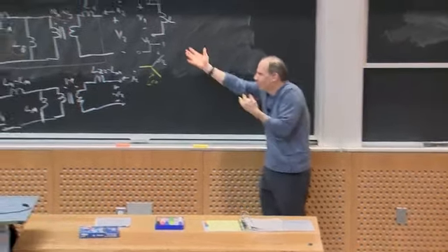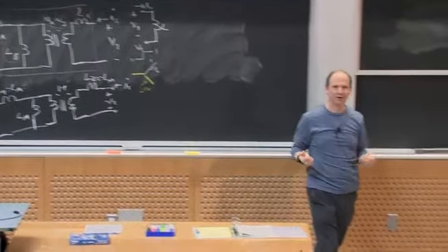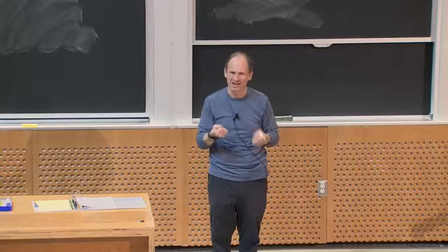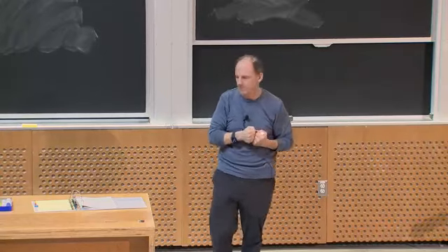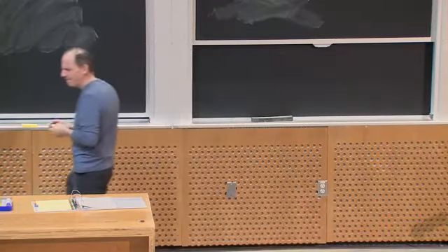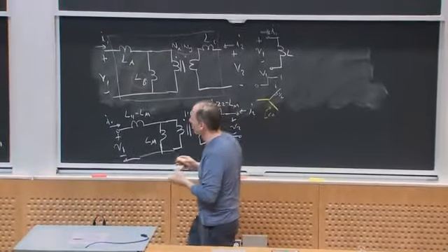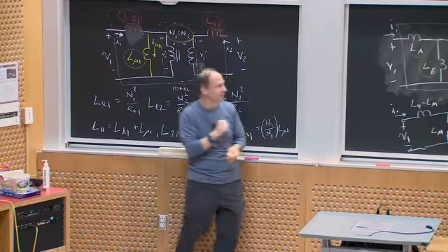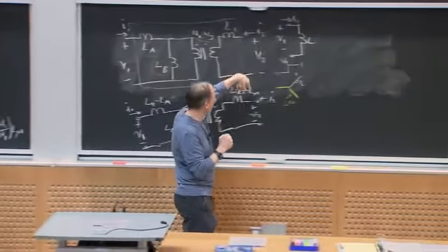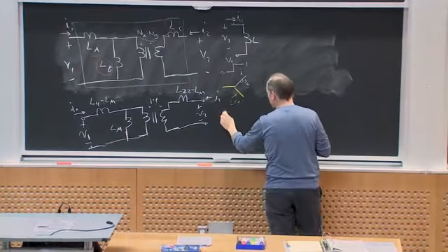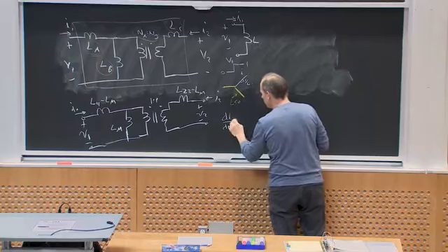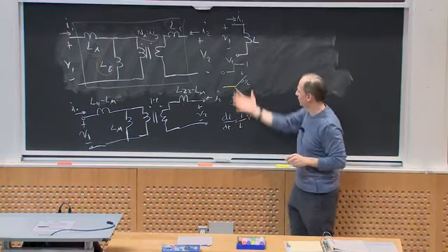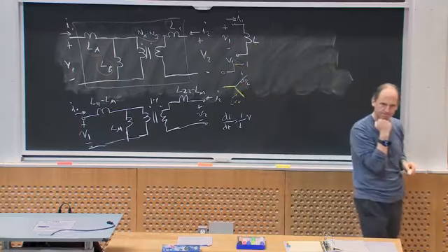So what do we know about an inductor? We know the inductance, as a practical matter, has to be positive for anything we're going to wind up with wires and cores, that doesn't have a source of energy inside it, okay? Well, what could I say about my transformer parameters? You can make a similar argument, right? Because what I really did here was I said di/dt is equal to 1 over L times V. That's the argument I just made about my single terminal inductor.